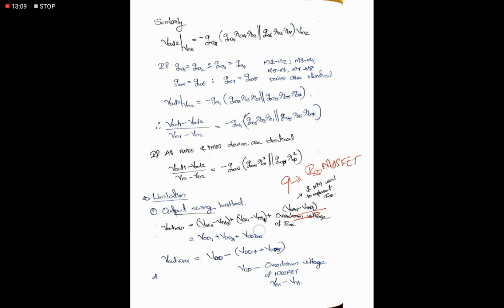Everything is fine. And the upper side is limited by 2 MOSFETs. Here it is expressed in terms of both sides. Both are fine. And the total swing is twice the one-sided swing, so the total output swing is 2 into the swing that we observed.